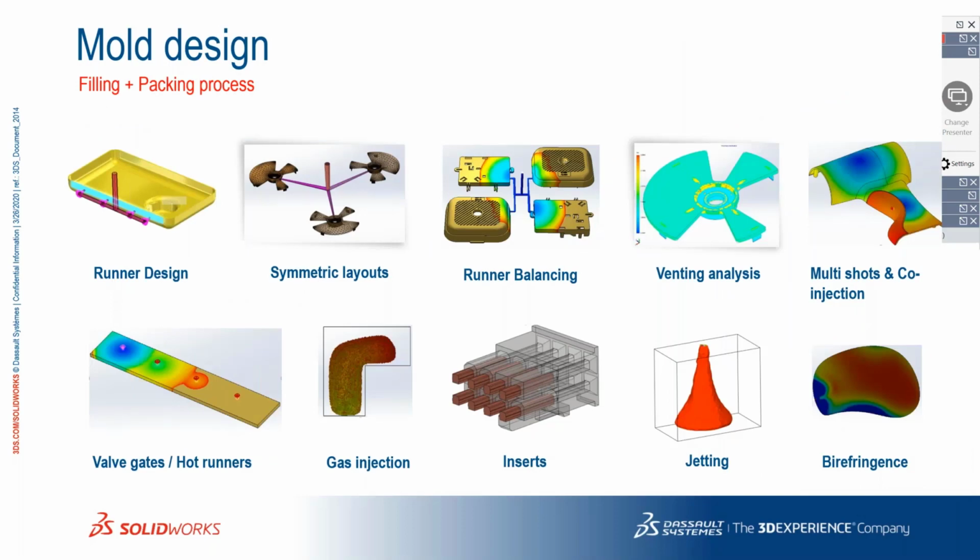Here I would like to bring in one more point. When I'm a part designer using the SolidWorks Plastics simulation, I can have only the filling process. I can analyze the filling process, where you can detect the defects only at the part level: what happens during the filling, what could go wrong, and how we can correct those things. But in the mold designer aspect, it is not only filling but also packing, cooling and warping, which we are going to see in the next slides.